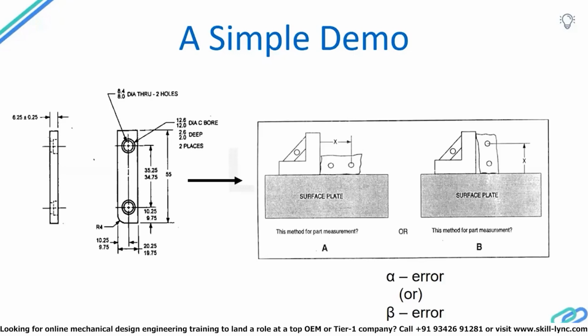For example, the square tolerance that we were talking about before is an illogical way of tolerancing, though it was the starting point of dimensioning and tolerancing. From there, we have moved on to cylindrical tolerancing, which is more logical and helps our manufacturing and interchangeability more. And like this, we have so many additional benefits from GD&T.